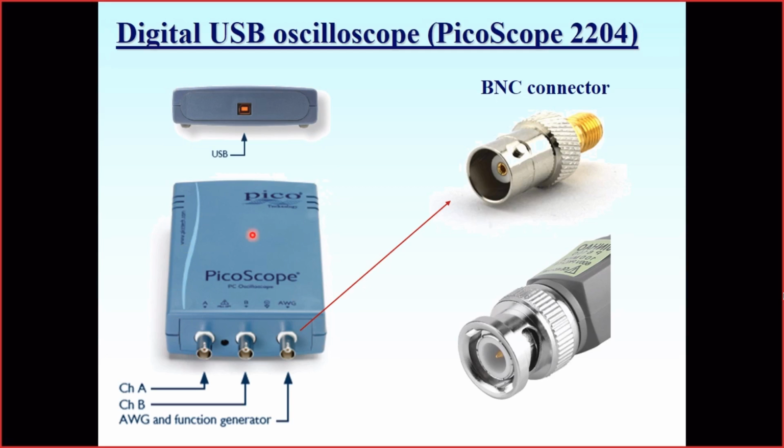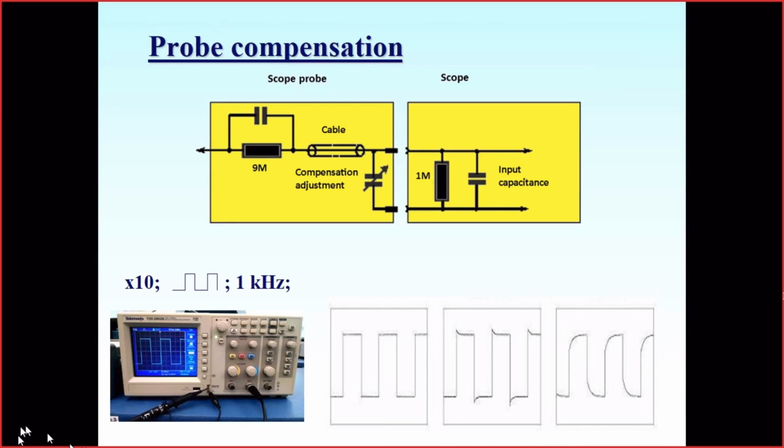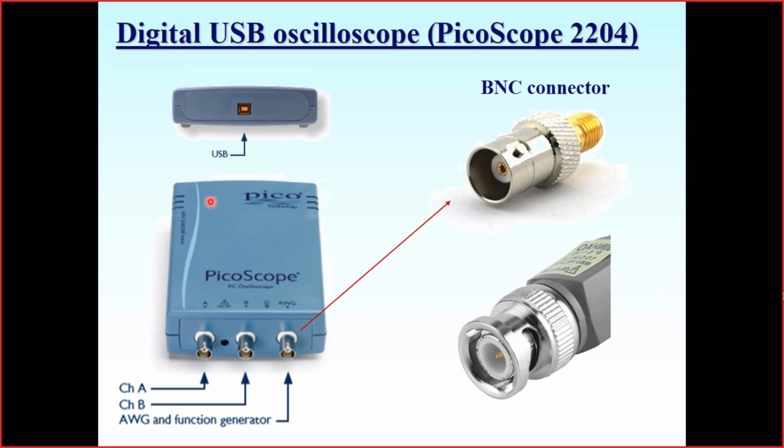From the side there is some hole where you put your probe, and it's the hole where this 1 kilohertz rectangular signal is generated. Or otherwise you may just generate it from your function generator.